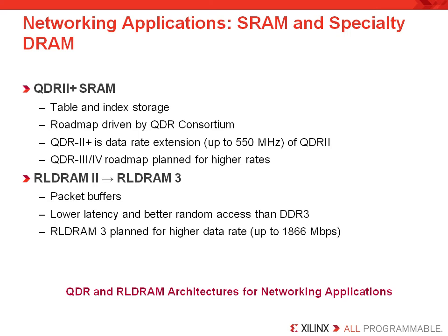DDR3 has a smaller dynamic memory cell. Its density gives it a big advantage, but its reads are destructive, and the memory cells have to be refreshed, and you have to do page management when copying data as well as other commands. So there is a lot of overhead in using a DDR3 memory in terms of functionality that must be built into the memory controller. DDR3 provides a huge capacity at a reasonable bandwidth, but with a sometimes unpredictable latency.